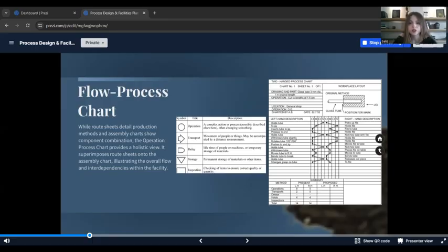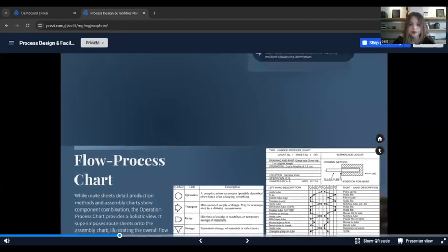Here's a two-handed process chart for cutting glass tubes. It tracks every left hand and right hand motion, useful for ergonomics and cycle time reduction. The summary table shows present versus proposed method, and the workplace layout diagram helps us redesign for efficiency.